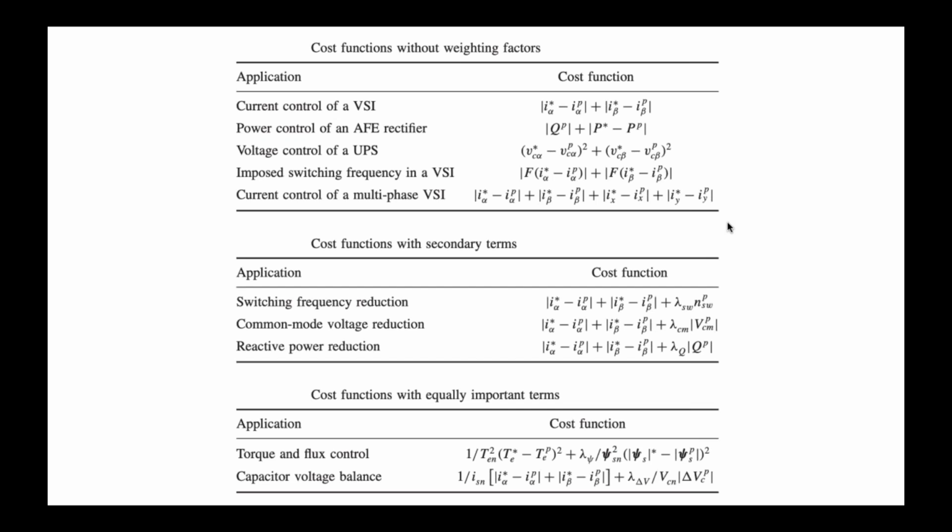For model predictive control, there is no particular toolbox, because your system and load vary, so the cost function and control variables also vary. In that case it is very difficult to use an inbuilt toolbox. You need to design the controller based on your system requirement.